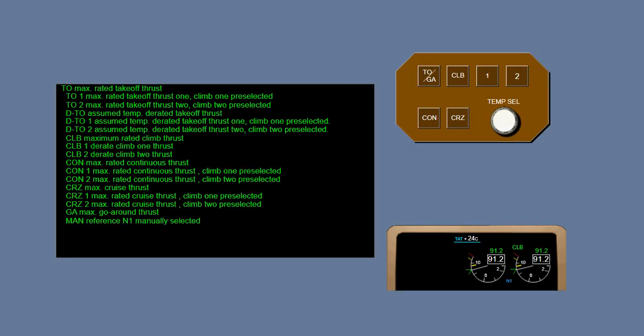The system is capable of providing 2 reduced climb thrust modes with the selection of the 1 or 2 mode switches on TMSP. With the airplane in flight in the climb reference mode, pushing the 1 or 2 switch changes the climb thrust reference from climb to climb 1 or climb 2 as appropriate. Similarly, you can reselect full climb power by pressing the 1 or 2 switch to turn off the reduced climb power.